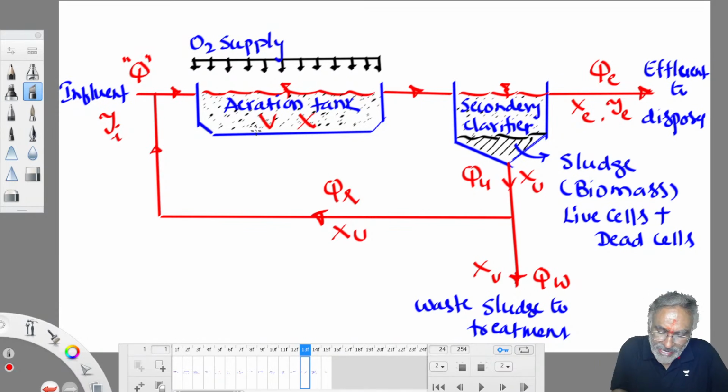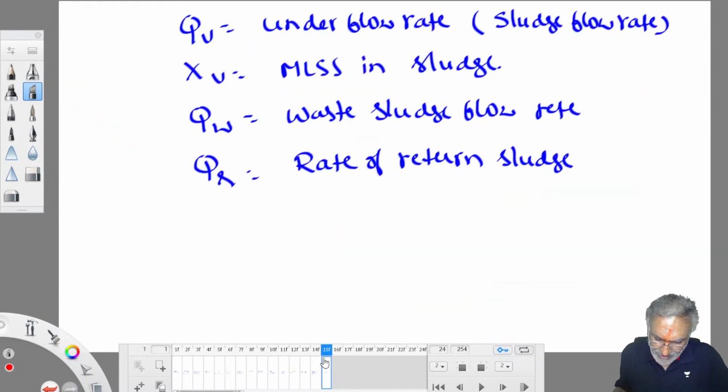Exactly the same way, the aeration tank is a milk bowl, and this XU concentration is the curd drop. If a small amount of curd drop is put into a large milk bowl, then the total milk converts into curd. Exactly the same way, a small amount of XU taken back to the process triggers the growth of a large amount of organisms. Understood now? Okay then. That's why it's called the activated sludge process. Deactivated live cells present in the sludge are once again activated by taking them back to the process to trigger the growth of new cells.